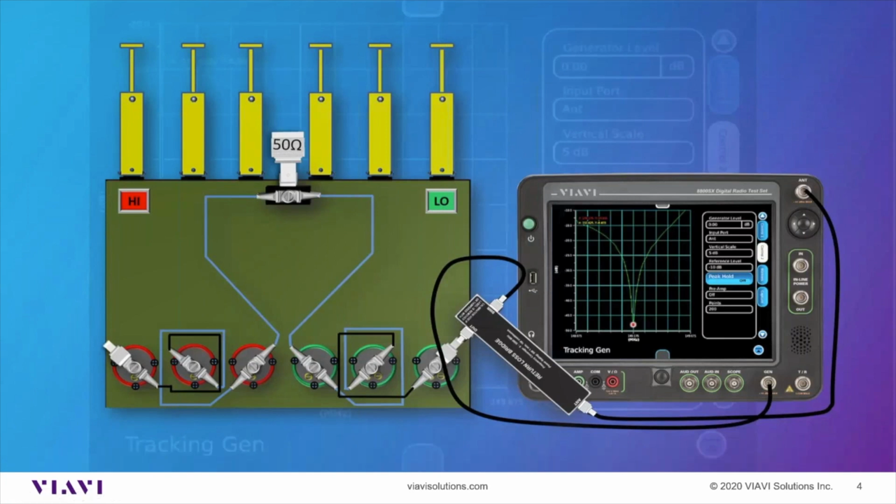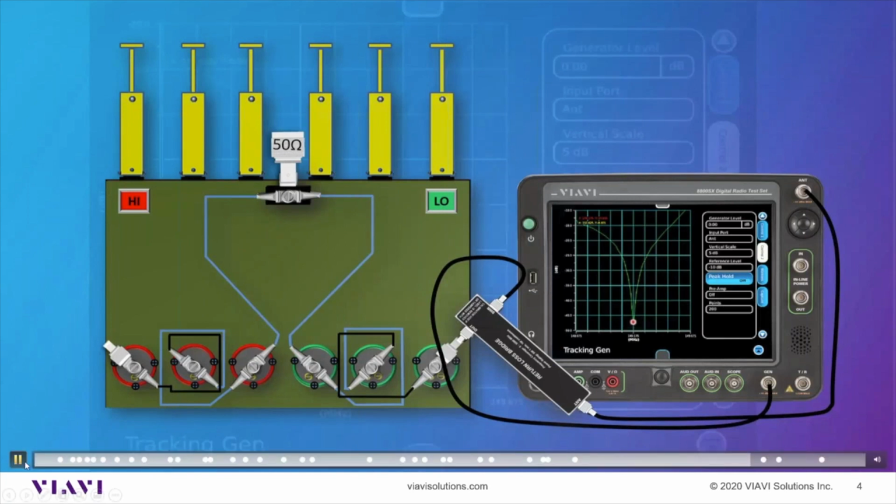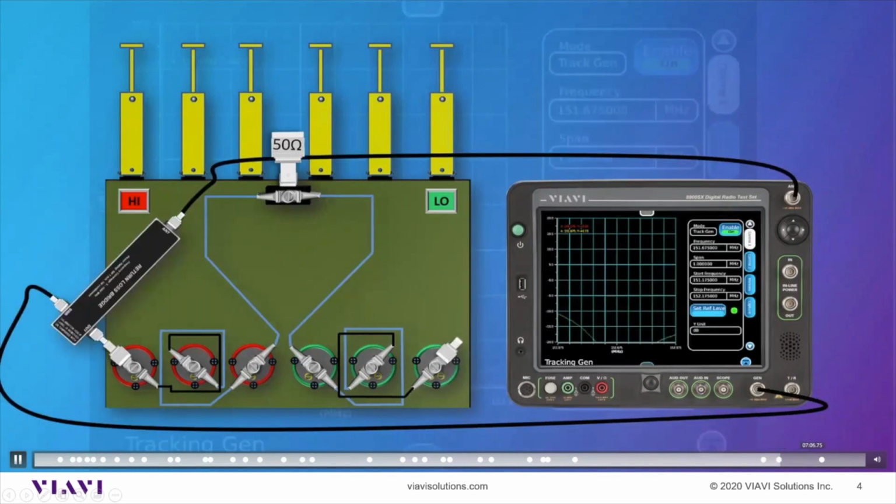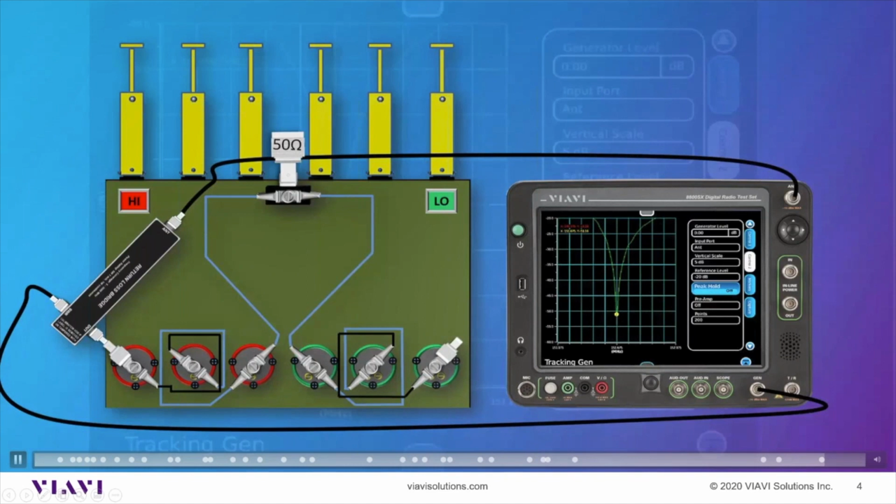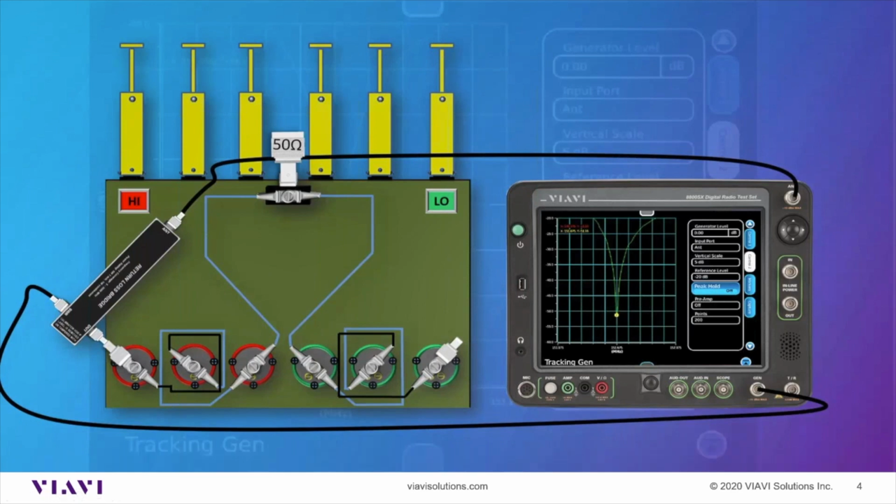And I'm not going to go through the whole thing on the high pass. I think we'll probably just show you what it looks like here. So go to the end over here, and that is our notch on the high side after I went through the tuning process, just like I did on the other one. And so I have both the high pass and the low pass retuned to my new frequencies.